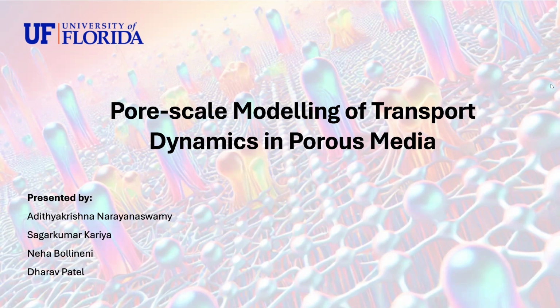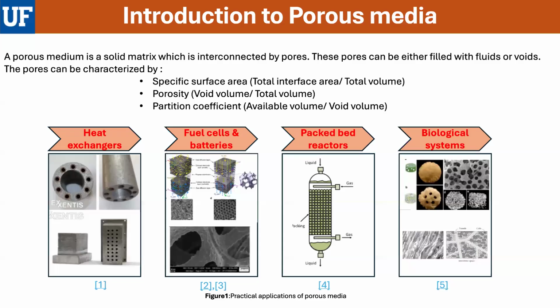So what is a pore? A porous medium is defined as the solid matrix which is interconnected by pores. These pores can be either filled with fluid or they can be voids as well. Based on the structure of the pores, they can be defined as passing pores, non-passing pores, and isolated pores. And based on the structure of the pores, the porous media can be characterized from the specific surface area, porosity, and partition coefficient.